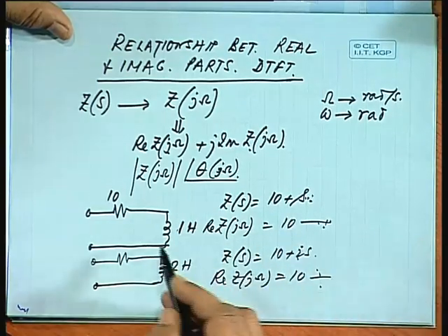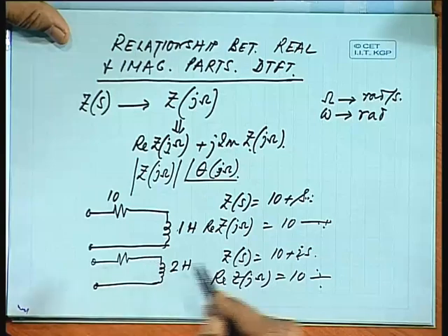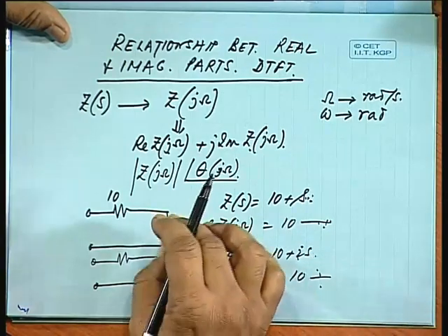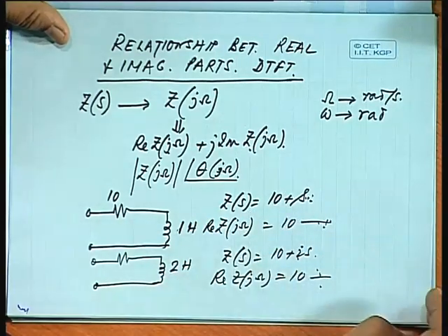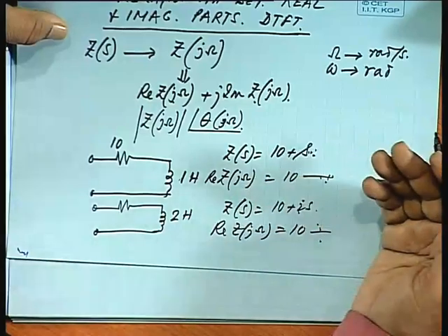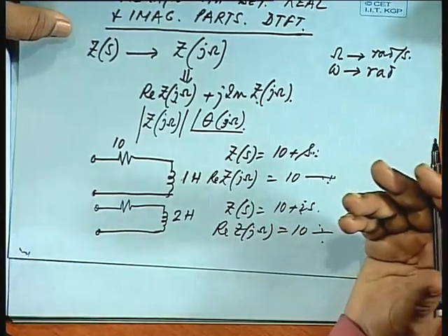Okay. So, we can evaluate those functions which will have just the minimum number of elements as reactive elements. We call it a minimum reactance function. Minimum reactance for the realized network will be possible. That means, we find out a network function. I have taken a very simple series element, it could have been much more complicated. So, given the real part, you can realize the imaginary part, where the imaginary part realized will have minimum reactance value. Anything you add any more reactance, the real part does not change.